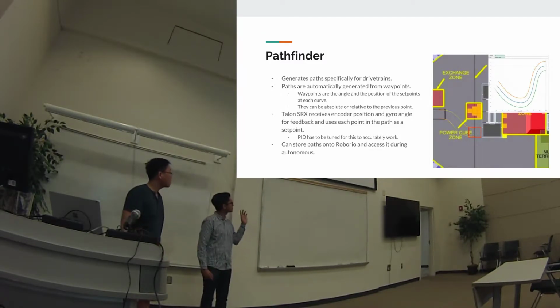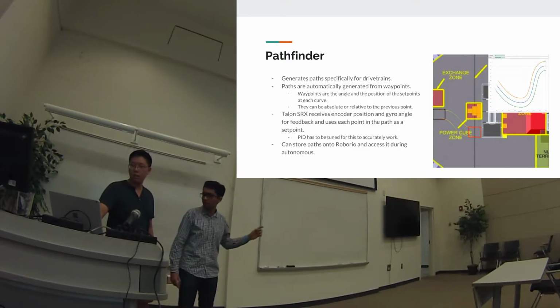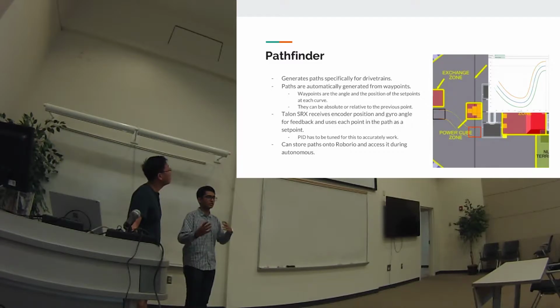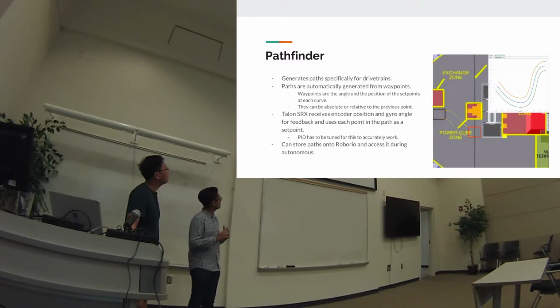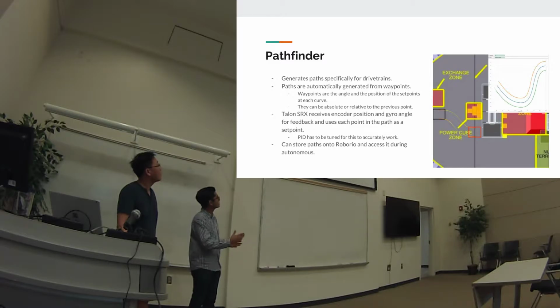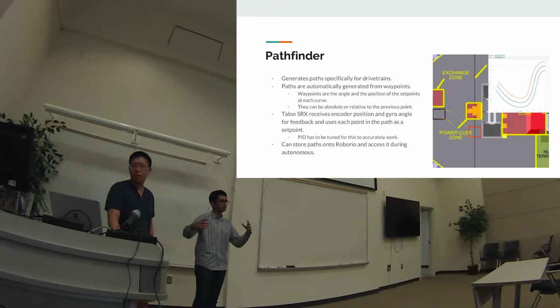Sorry, also just to put all this into context, if you go back to our robot example, if the drivetrain were to use motion magic, the one-dimensional system, the problem is it would still take into consideration the velocity and the acceleration of the drivetrain, but when we go towards the scale, it runs that simultaneously, driving while turning to it. When you're creating the path, it seems like it's not taking into consideration the angle while it's driving, but it's actually using the NavX with the Pathfinder library.